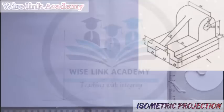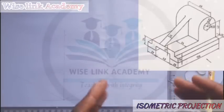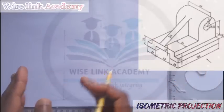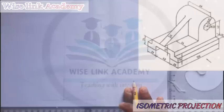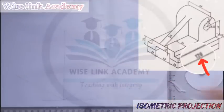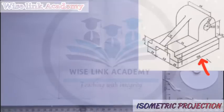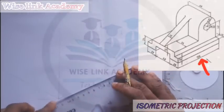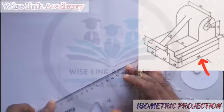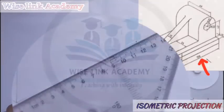So, having drawn your isometric axis, what's next? We said for the construction of isometric projection, your first task will be to draw your isometric axis. Next, your task is to measure out the length, breadth, and height of the given figure. First things first, my entire length is given to be 120, from here to somewhere here. As you can see my arrow indicating, I'll measure out 120, which from here is 0, so somewhere here is 120.